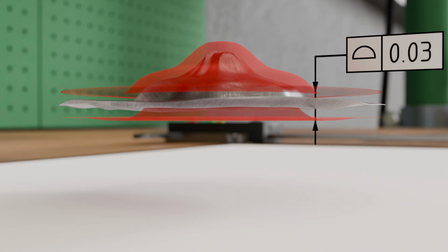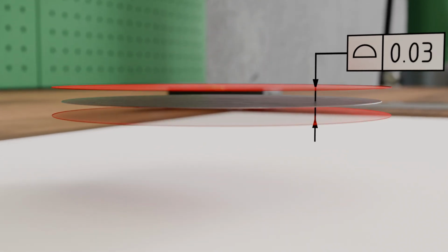The surface profile tolerance can basically also be applied to a plane. When overlapping the spheres, two parallel planes result, whose distance corresponds to the tolerance value, and within which the actual geometric element must lie. This ultimately corresponds to the definition of flatness. Thus, flatness can also be tolerated using the surface profile tolerance.